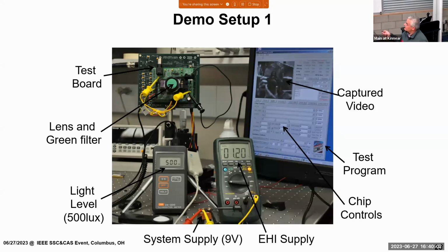Well, if you increase the light level, your power consumption also increases. Because instead of a lower 8-bit transition, you have all 10-bit transition for your pixels. As a result, your power is going to increase on the ADC side. But also you're going to be harvesting more. For sure, yes. More energy. But your power consumption is going to increase.